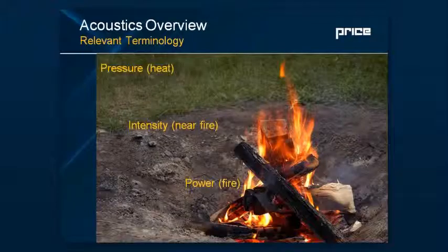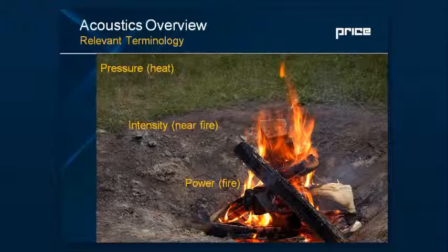A lot of times, too, you hear sound power, sound pressure, sound intensity, so just a quick, easy way to understand the differences. Power is essentially, when you're thinking about a fire, like describing how much heat is generated by that fire. So there's no way to really measure sound power. Instead, we measure sound intensity, and then we go backwards because we know the distance from the source, and we're able to then determine the sound power of that source.